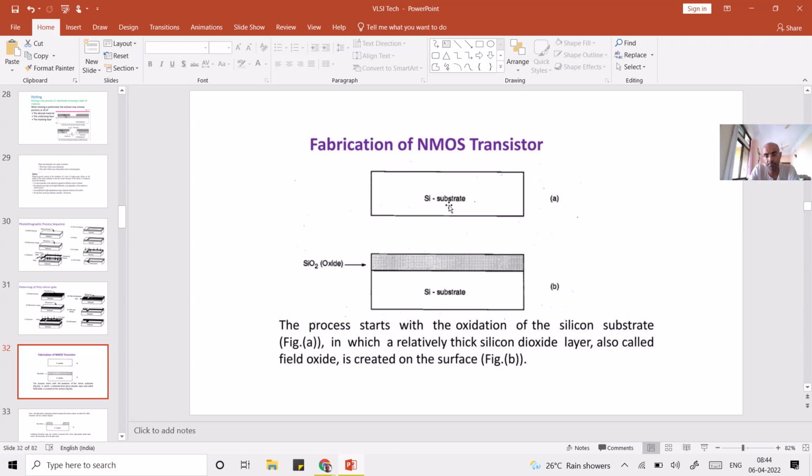The reason is that the 111 oriented wafer is not that costly, because it is easy to grow. The basic reason is that when you have the 111 surface, the distance between the surfaces is very small, and if that distance is very small, the adherence of the material is very good.